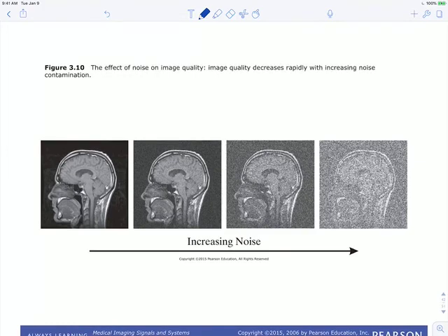All right. Okay, so now let's talk a little bit about noise. Noise is just a fact of life. There are different types of noise, but no matter where you go, there's always something called thermal noise, which is just the random motion of molecules. Okay? That affects both the electronics and also the sample you're looking at. For example, in a human body there are lots of random currents going around all the time, so an MRI system will pick up all that noise as well. Even if you design the best system in the world, you're still going to get noise from your sample in many cases.